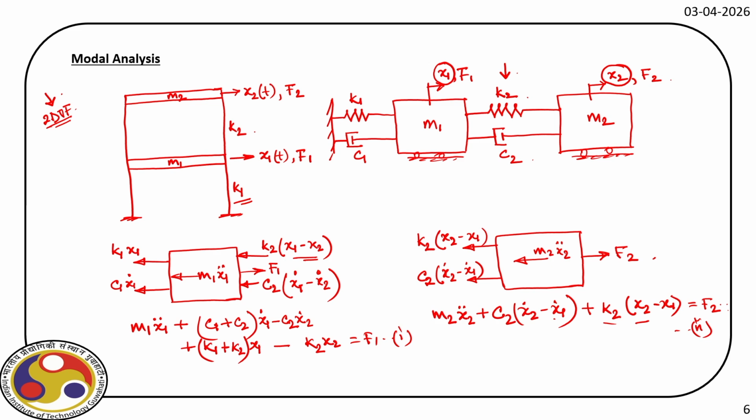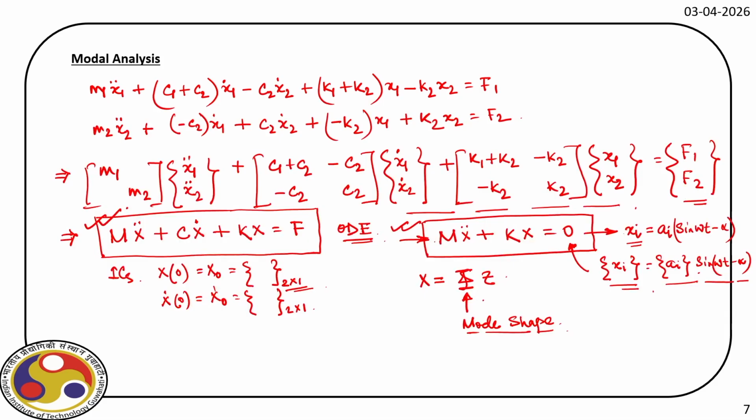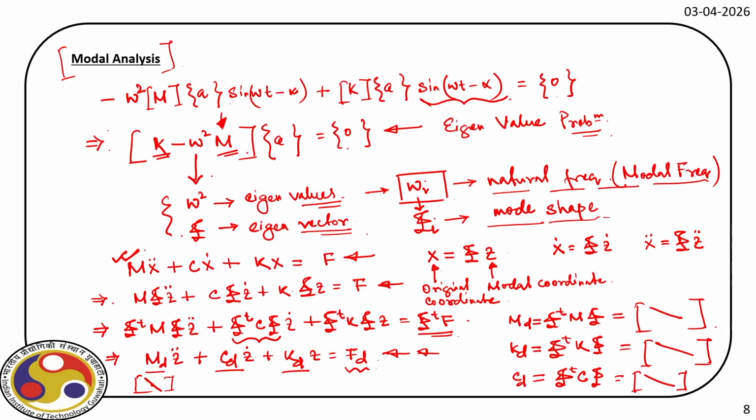Corresponding to each natural frequency, we can find the deformed shape, which is here phi i, and that is what we call the mode shape. In fact, we'll solve in a minute the same building that we modeled and did the static analysis of using STAAD.Pro software. For each natural frequency, we'll also plot the mode shape and see how the structure vibrates in its mode.